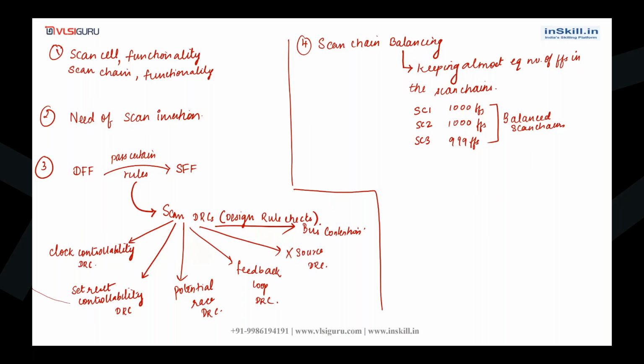And why do we need to go for scan chain balancing? We need to go for scan chain balancing to reduce the test time.